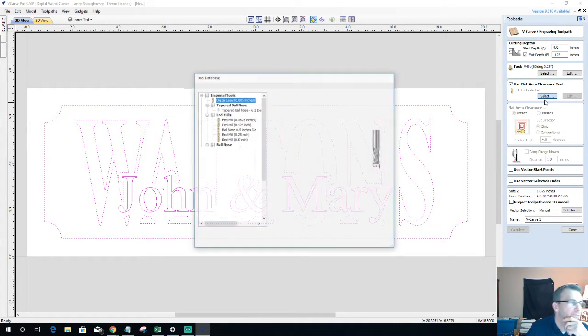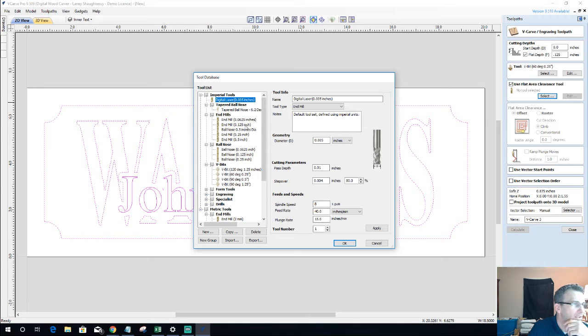Now for this, if you don't have one, I highly recommend one day, if you're ever out at Lowe's or Home Depot, not a very big fan of their bit selection, but you can order them online from Digital Wood Carver, Tools Today, Rockler, and all, but running down to Lowe's and getting yourself a small 1/8 inch end mill. 1/8 inch end mills are nice to have in your arsenal of tools because they get into small areas and things. You can get end mills down to 1/16 of an inch, but 1/8 inch is a nice standard little bit to have in there.